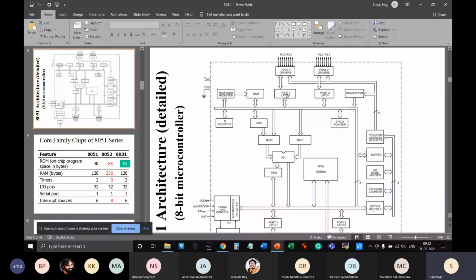So I want to save the data in accumulator. The data will get latched, and then in a subsequent clock cycle it will be read, because at that time the accumulator may not be ready also. Assuming it's not ready, then timing and control will apply read to this latch and write to the accumulator. So MOVX will do this thing.